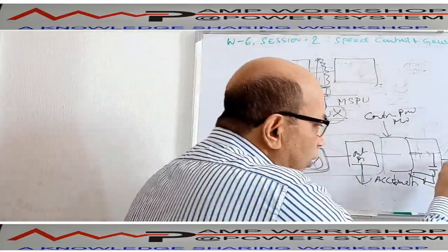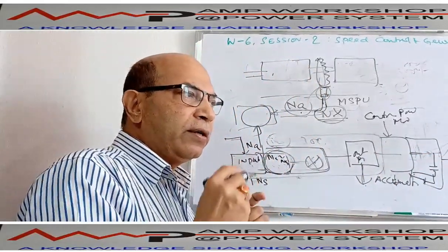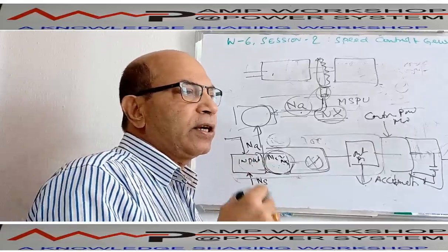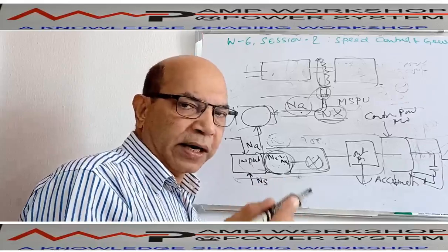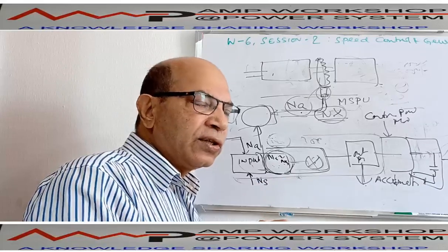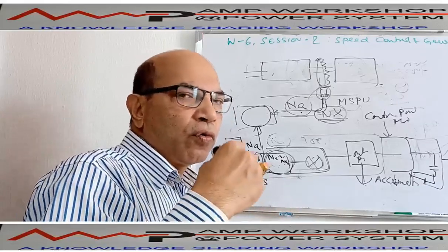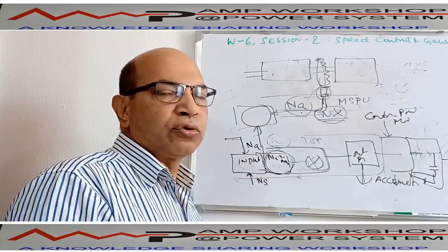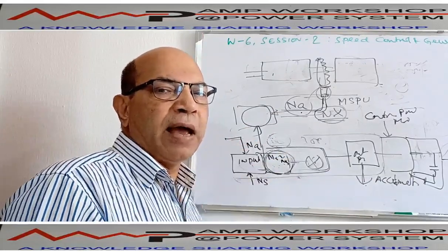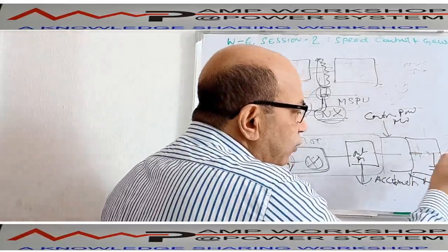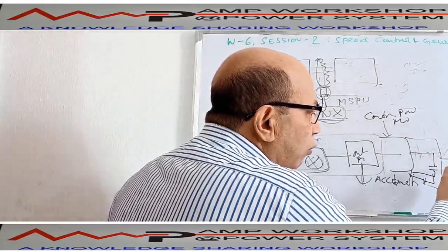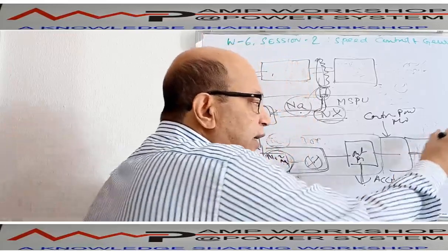Again, with this governor, when there are multiple generators running and one generator's speed is getting changed, if it is coupled or paralleled with other generators, this change will be transferred to the other machines also. So there will be communication amongst the governors of the other machines. So there is an interface from this governor to other governors or the load sharing module, you can say.